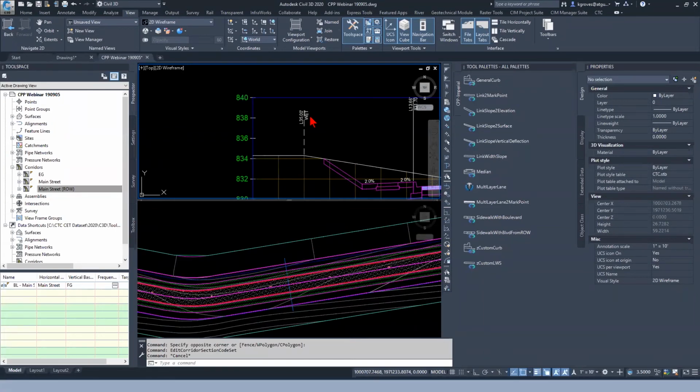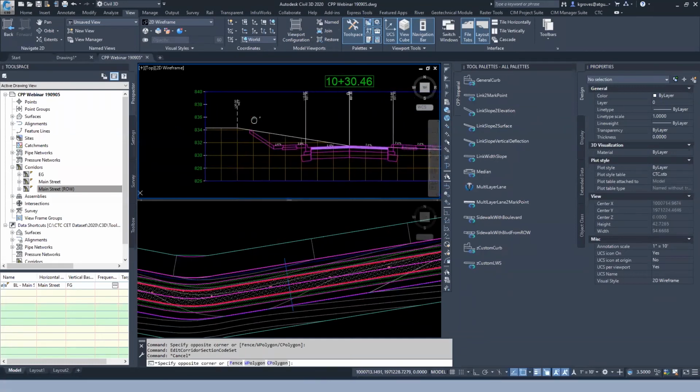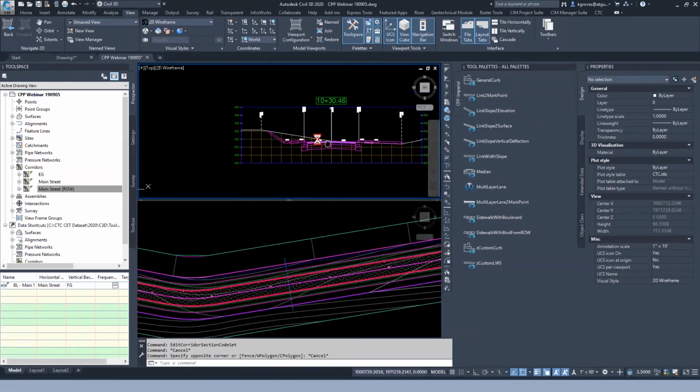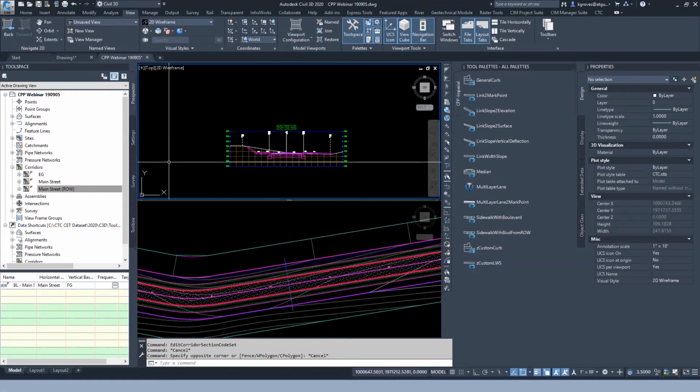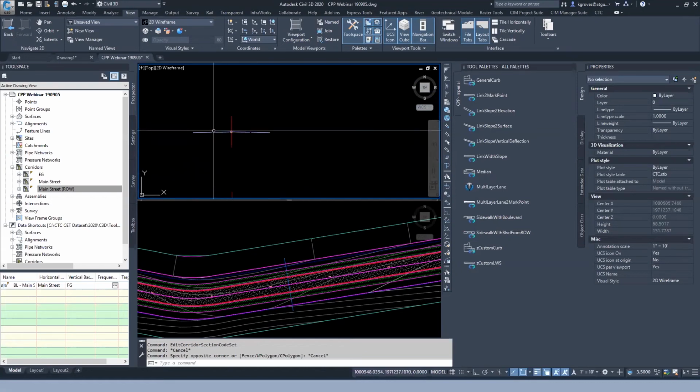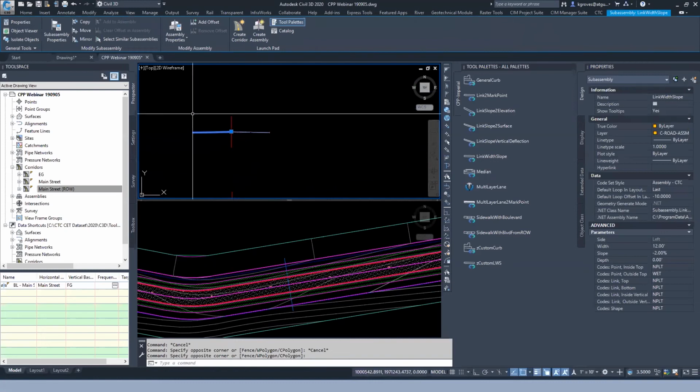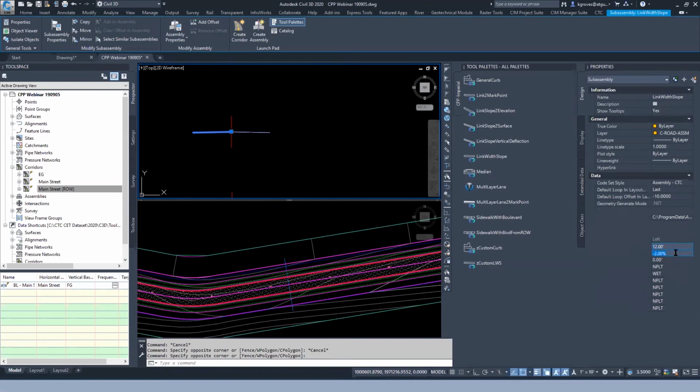So still getting some more questions on this whole corridor to target your other features kind of outside of your primary. So if you don't target the surface vertically, you're just going to get whatever happens as part of your assembly. So your assembly is your typical cross section. And with this, you get to specify parameters like width, slope, depth, the rest of that stuff.